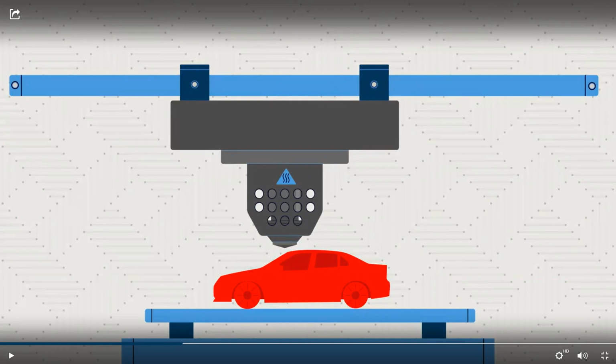Then it's going to go through a head. This head is heated, and as it comes through here, it's going to lay down that plastic layer by layer. You kind of saw in this video that the bed actually moves, but in our case, our head moves. This bed moved up and down as opposed to the head moving. In our case, our head moves up and down, left and right, in and out. So our bed stays in the same place.